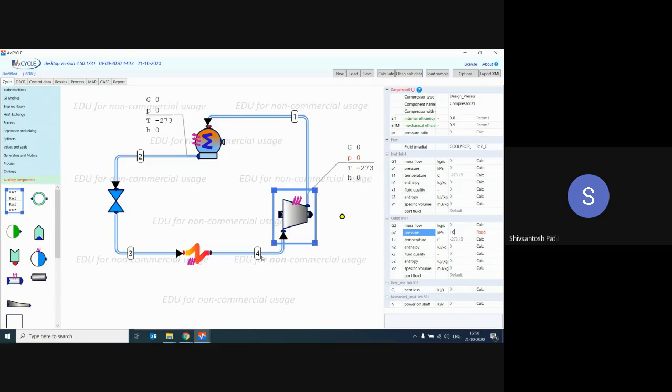At the inlet, this is link 4. At the inlet link 4, I'm keeping, for example, mass flow rate as an initial value, 0.05 kilogram per second. So the 0.05 kilogram per second is the mass flow rate of the fluid, and the outlet is the fixed pressure. Mass flow rate you specify only once.